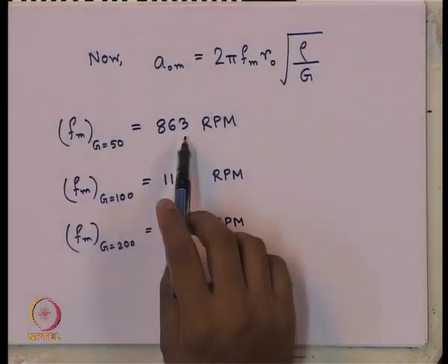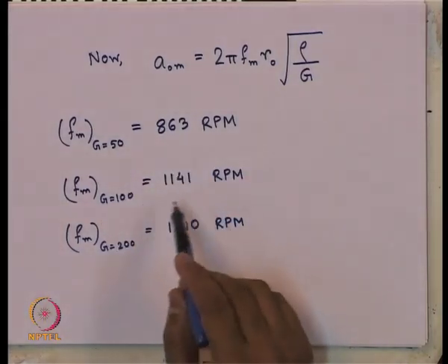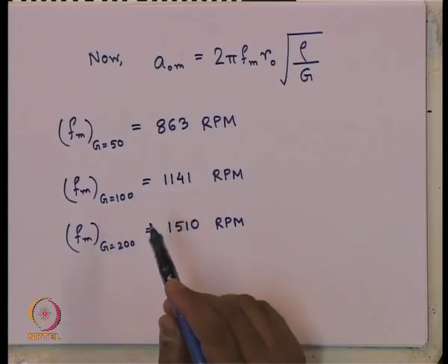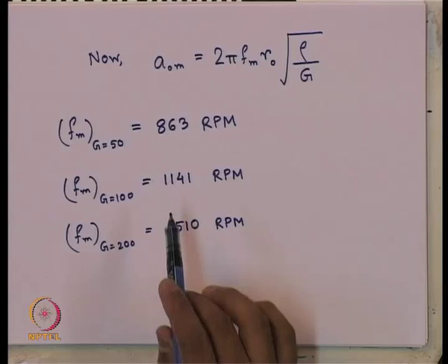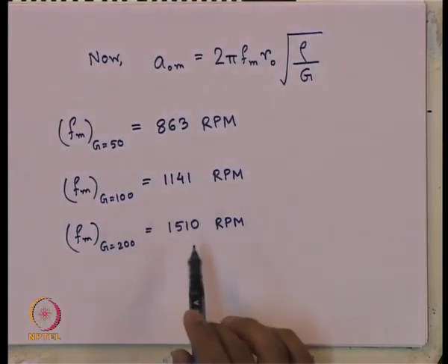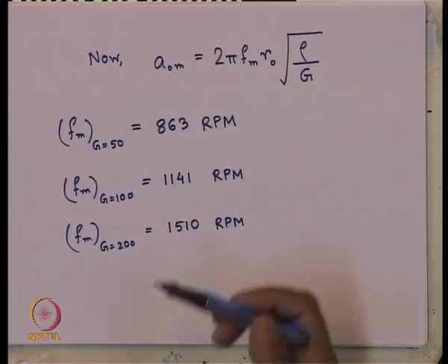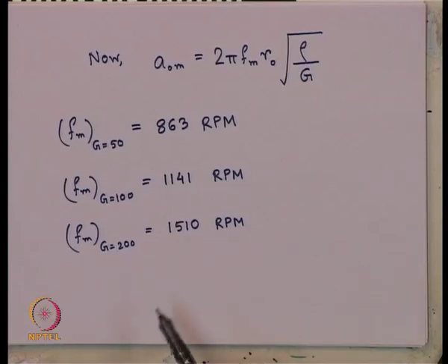Whereas, for this type of soil it is allowed, but this type of soil also it is somewhat permissible. So, remember how much factor of safety we are planning to provide. Depending on that, you can decide and give your judgment. So, here your judgment will come into picture, because when you are commenting on the design aspect, looking at this resonant frequency, you have to give comments on where to keep your operating frequency, in which range, and so on. So, that is why this computation of resonant frequencies also plays an important role here.